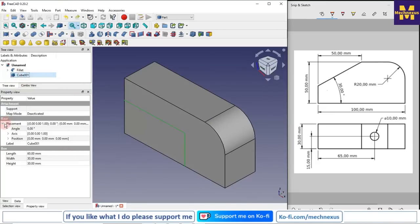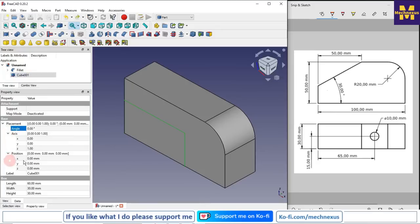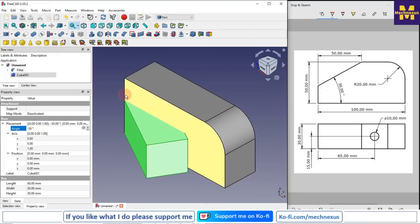Now if we go to the placement tab, then we can see the axis and positions option. So now we are seeing the rotational axis is Z. Now if we change our angle to -30, it is rotating across the Z axis. So this is Z axis as per our UCS. Then it is not as per our desired result, so we will change it.